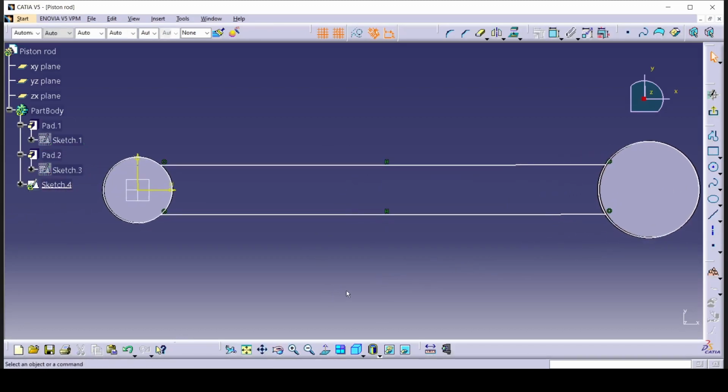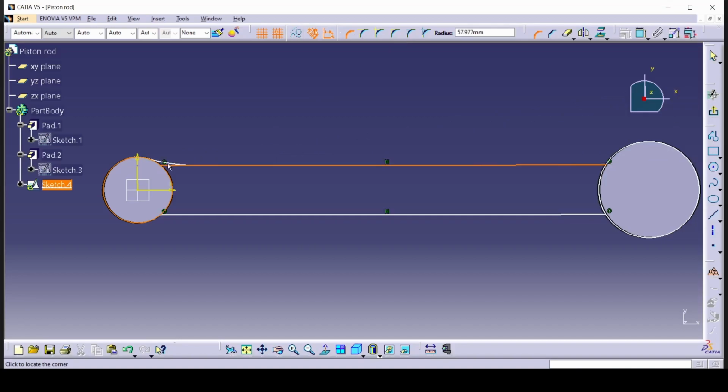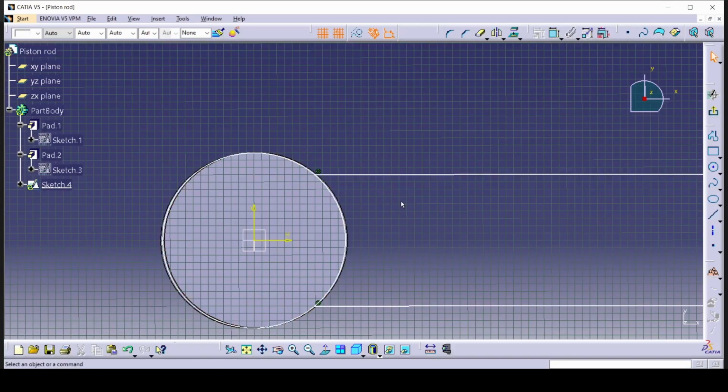We're getting pretty close to the end. So the first thing you'll have to do is select this part and select this. So we can make the small little radius of 24, which is also 24 on this side, remember. So write in radius 24. Do the same thing on the other side. As you can see, we lost this portion right here. So let's repeat this, I guess.